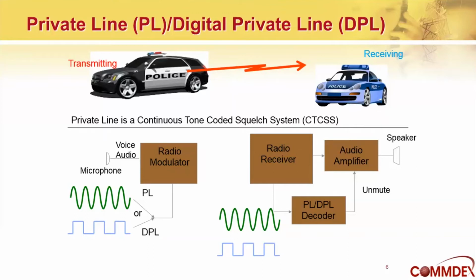We equip receiving units with the ability to decode only those signals that have that tone-coded squelch on it. Therefore, even though many people may be talking on the channel at the same time, only the ones with our selected tone-coded squelch can be heard by it. So we're not providing security. The channel still has many people on it, but we can only hear those within our own group.